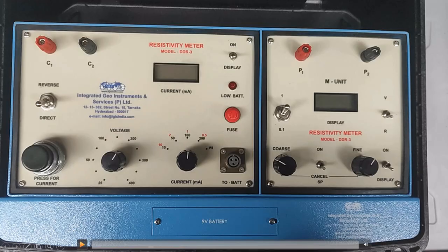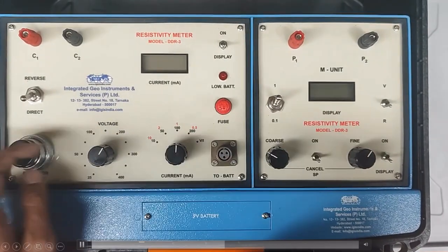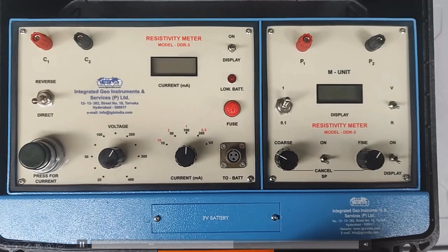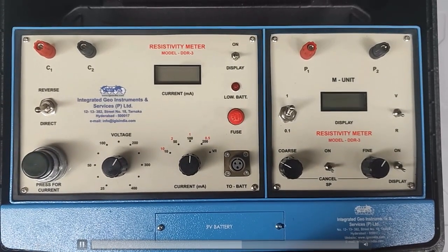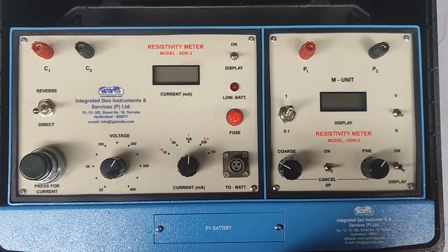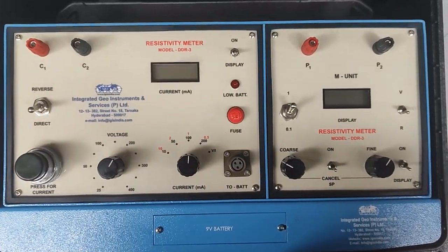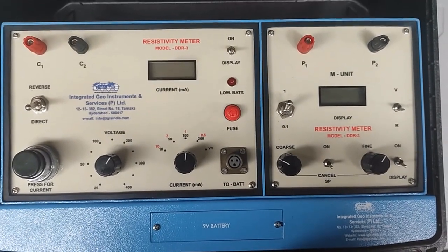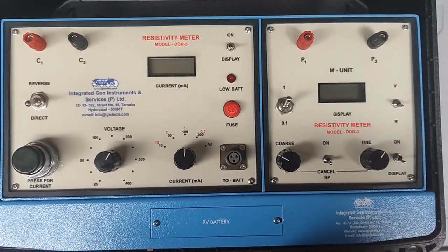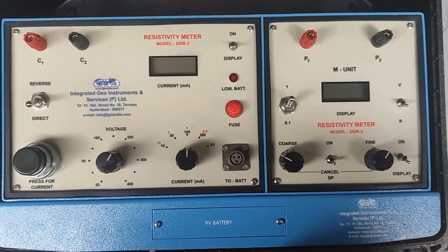In the process, the metal to solution potential or the self potential is usually unidirectional during a shorter time interval, and they get cancelled in the measurement. But these readings get averaged due to positive and negative cycles, direct and reverse. The use of alternating current will also help with SP compensation.